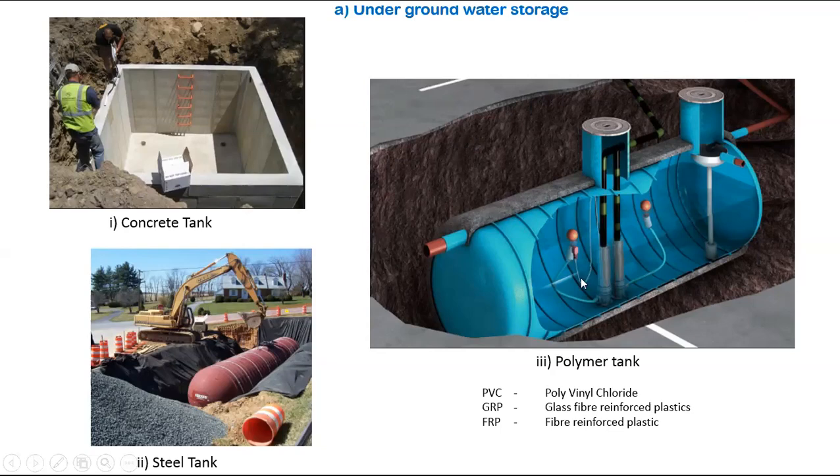After placing this tank, we have to put in a pump to suck the water. A submersible pump is recommended for sucking the water, lifting the water. It's a positive suction pump. Submersible means priming is not required, so that's why we are using a submersible for this one. This is the vertical submersible pump type.